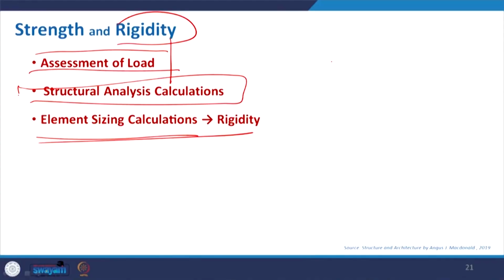Like, okay, we know RCC, there will be concrete. Now, in concrete, what grade of concrete will we use, whether it will be M20 or M25, M15, what are the different grades of concrete. Basically it depends on the mixture also. M20 means that after its curing it will be able to have a compressive strength of 20 Newton per millimeter square.